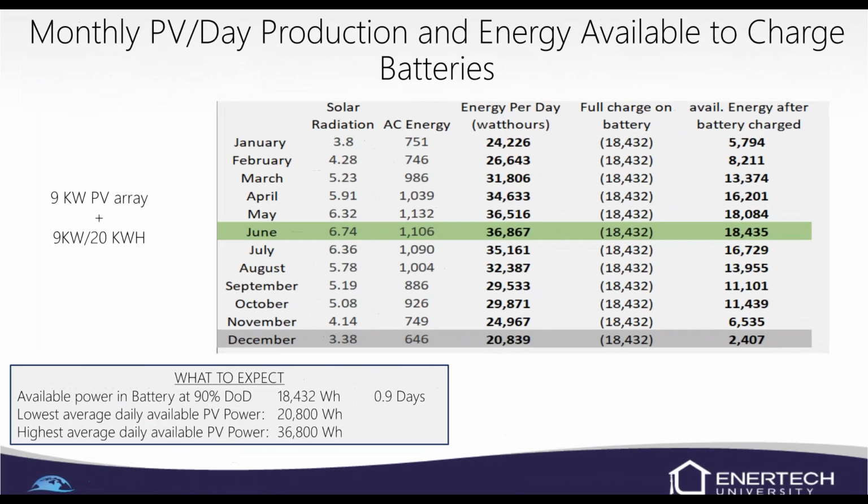Make sure you get a power bill with that. That'll definitely speed up the process of designing and making sure we've got enough batteries and the right inverters and that kind of thing. So a copy of the power bill is critical on that. Just a full printout of the actual bill itself, that way we can see the structure of the bill. It's important to see both the 12 months usage, but also the PDF copy of the bill, if at all possible. Otherwise, we can't really see how the bill is structured to see if batteries make sense or not.